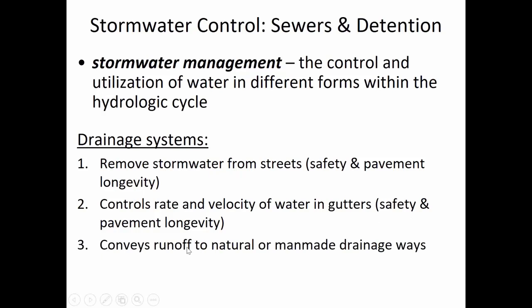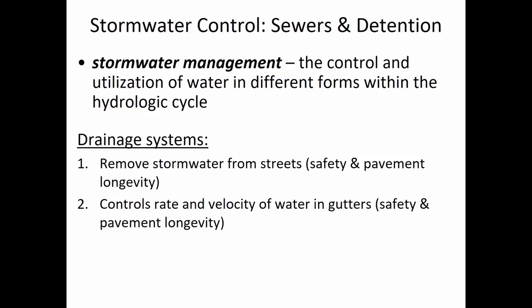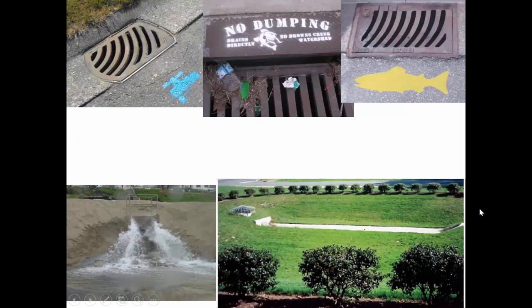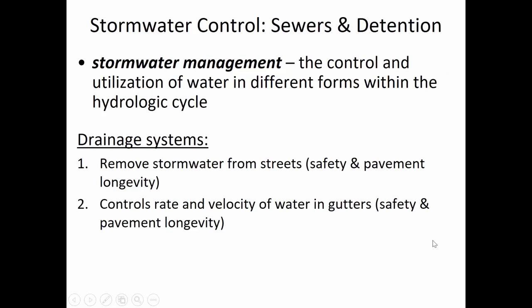Now the networks are going to discharge to the natural waterways, but sometimes there's an effort made to try and clean up the water a little. In stormwater runoff, usually what they try to do is separate any kind of easily settleable solids like grit and sand. Just finding some place like a pond, such as this, the grit will settle out. Occasionally this pond would have to be maintained, after a very large event, where the water would be pooling in here and sand would be settling down. They may have to excavate the amount of sediment that had accumulated there.